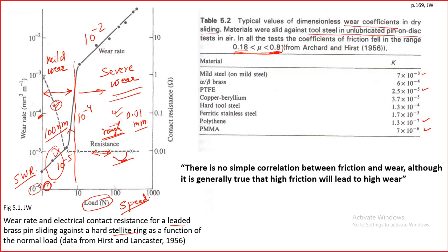So this is very important to understand, because often in many of the theoretical modeling, when people are doing it and they need a value of mu, many times people just take some values, 0.3 or 0.5, 0.35 or sometimes 0.25, but these differences are very, very small in terms of coefficient of friction, yet in terms of wear it can be a very big change. And also if you calculate the forces required or energy required, they will also be very different, a very wide difference.